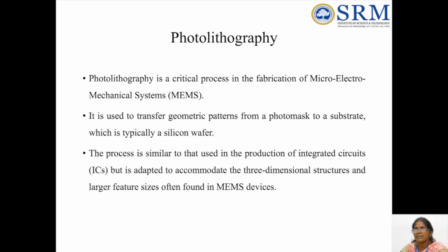Photolithography. Photolithography is a critical process in the fabrication of micro-electromechanical systems. It is used to transfer the geometric pattern from a photomask to a substrate, which is typically a silicon wafer. The process is similar to that used in the production of integrated circuits, but it is adapted to accommodate the three-dimensional structures and larger feature sizes often found in MEMS devices.